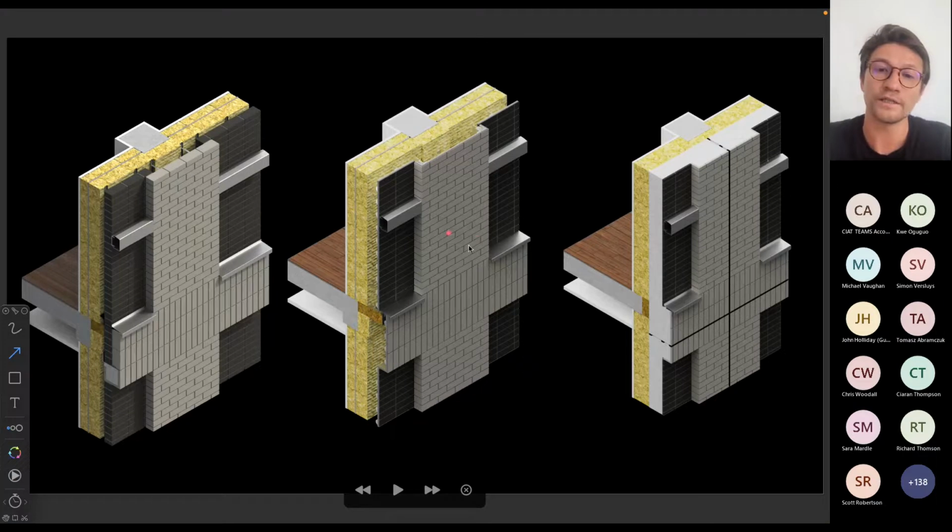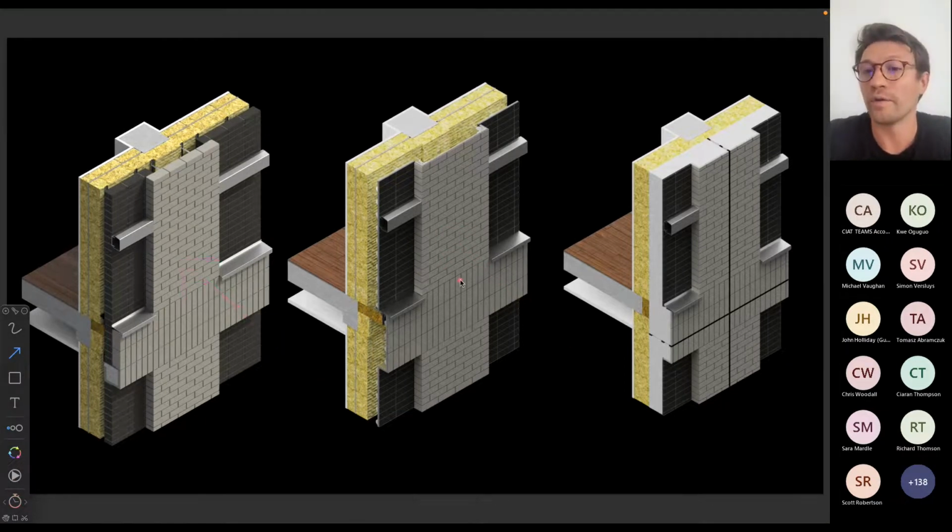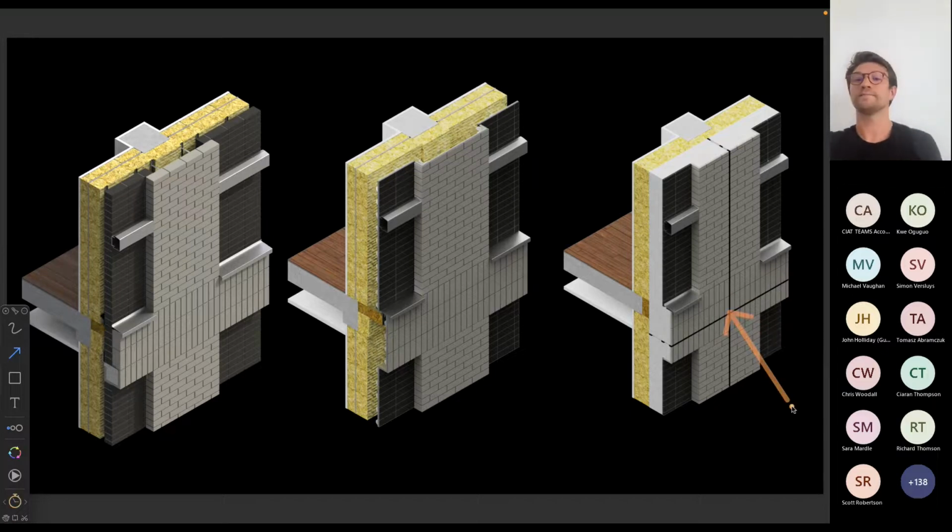For mid-rise, we are looking at brick slips or masonry veneer facade, or at precast concrete if it's very repetitive and high-rise, or if it's a really complex brick pattern. And if it is really high rise, a skyscraper that still requires a brick veneer, one would need to consider a unitized assembly with the brick slips fixed to it.